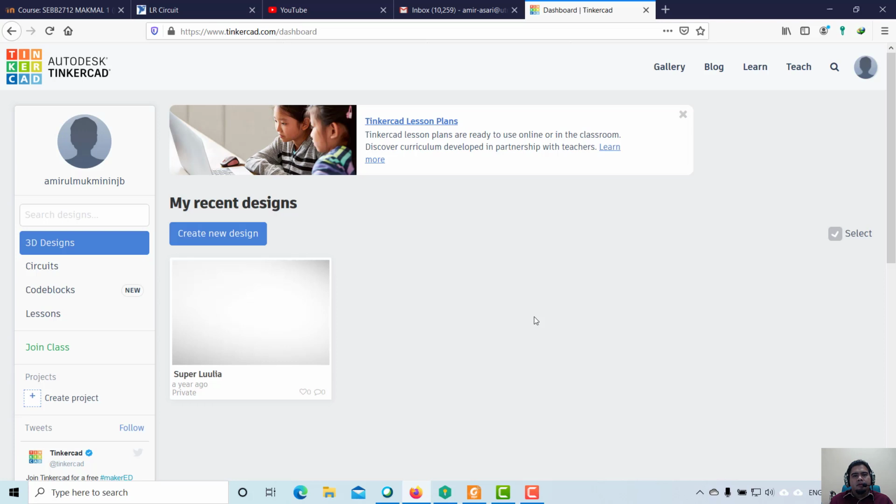on the same experiment? It is because the one that is closest to the physical experiment is TinkerCAD, but we also need to do the experiment using Multisim because the accuracy of the result in Multisim is better than TinkerCAD, especially for experiment 1, whereby you need to use the oscilloscope, and from the oscilloscope you produce a graph, and then from that graph you need to measure the voltage according to the tau you have calculated. That feature you can only access on Multisim, but you cannot access it on TinkerCAD.